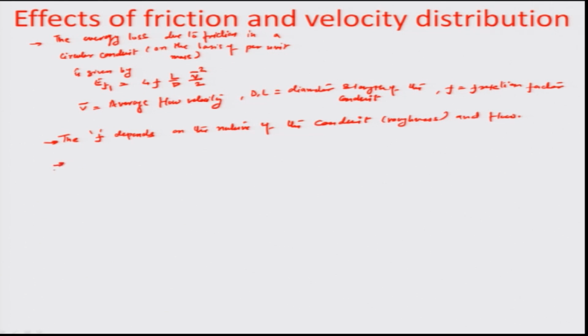Okay. So, if I just were to recall the way that we had set up the horizontal gating problem, so this right here was the vertical gating system designed, where we talked about the point 1 which was somewhere on the top of the pouring basin, and point 2 somewhere at the beginning of the runner, and obviously point 3 which was somewhere just before the entry to the mold.